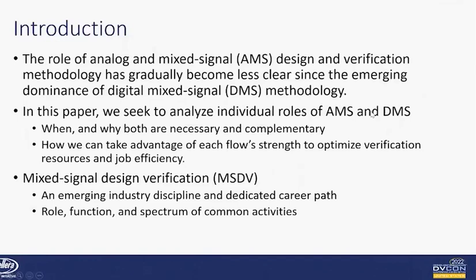The AMS methodology has perhaps existed from the very beginning of mixed signal IC design practice. In general, the AMS flow runs with either behavior models, say Verilog-A, or SPICE primitives. It has become less favored in modern IC verification flow because of its slow speed due to the SPICE simulator, and its role has become less clear since the emerging dominance of the so-called digital mixed signal, DMS, methodology.